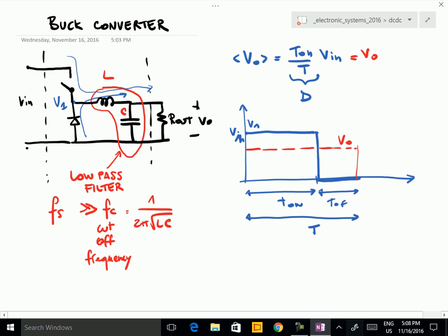There is a slight variation, because of course the low pass filter is not ideal. It suppresses the harmonics but does not eliminate them. Therefore you have some slight ripple, but for our purpose it can be neglected.